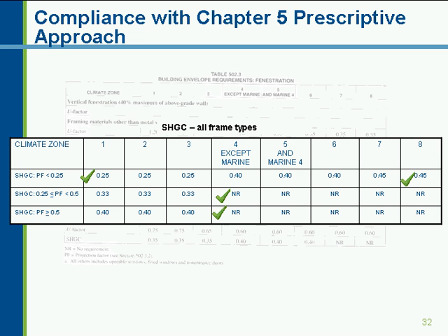If you have display glass for retail space, for example, and you want relatively clear glass, not tinted or glass with a low-E coating, installing a permanent overhang over that glass will allow you to have relatively clear glass, so you can actually see through the display windows into that building. So that would be one reason why you'd want to put in a higher SHGC glazing, then offset the energy loads by putting an overhang over the glass. For skylights, you're limited to 3% maximum of the roof area.